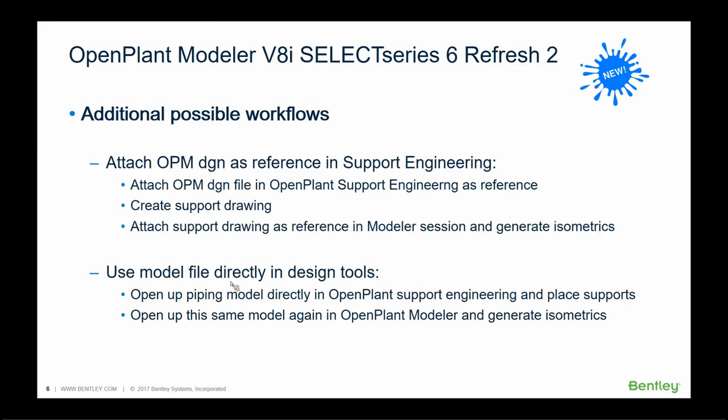With SS6 Refresh 2, we support both the iModel workflows as well as the DGN-based workflows with OpenPlant support engineering. In fact, you can even open the same DGN if for some reason you want to work in the same DGN in OpenPlant support engineering and place supports directly in the same DGN file.